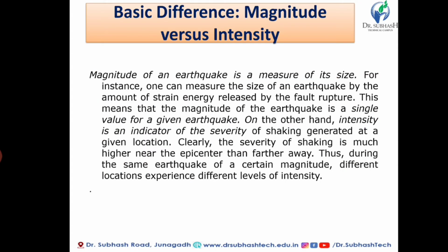Next, the basic difference between magnitude versus intensity. Here we already described these two phenomena, what is magnitude and what is intensity. Now we will discuss the basic difference. The magnitude of an earthquake is a measure of its size. For instance, one can measure the size of an earthquake by the amount of strain energy released and by the fault rupture. This means the magnitude of an earthquake is a single value, it should not change.